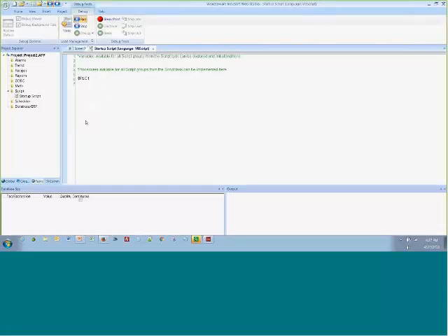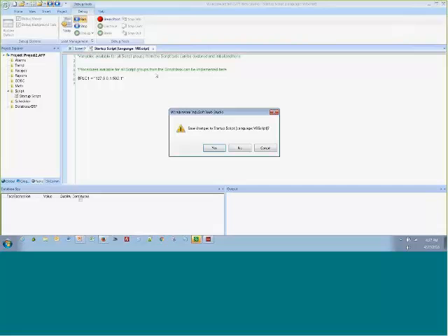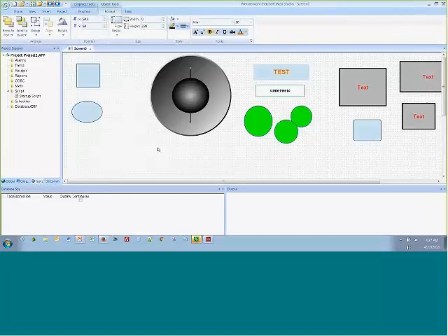So I'm going to choose that from IntelliSense, and then that is equal to, inside of double quotes, my PLC, which is actually a simulator, so it's going to be my local loopback address, port 502, PLC1, and there we go. So that'll define that when the project starts, and we'll say OK.